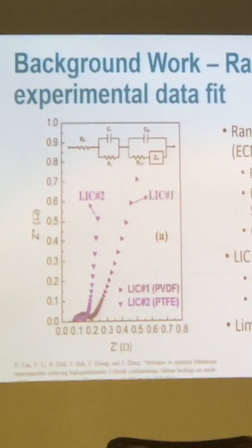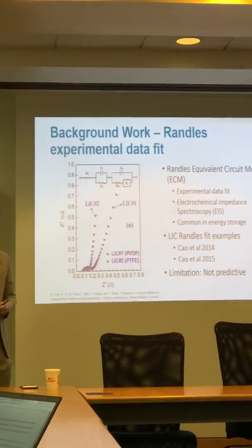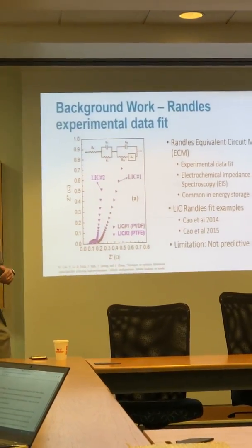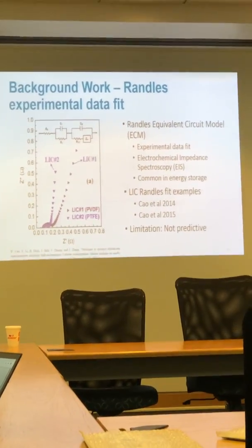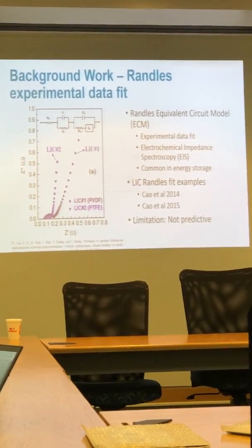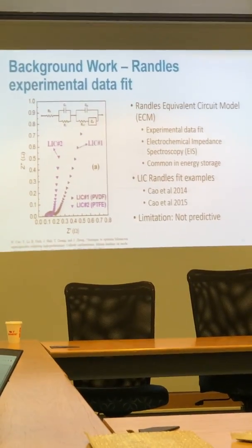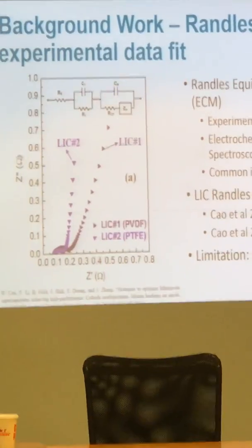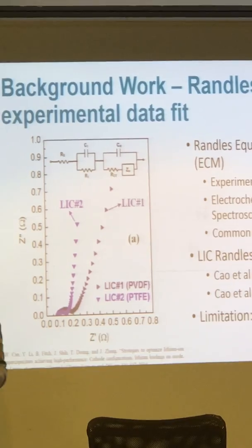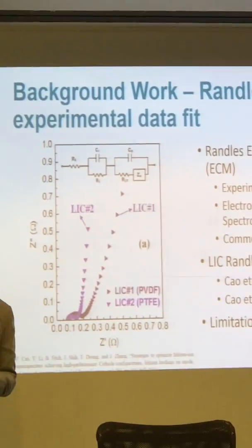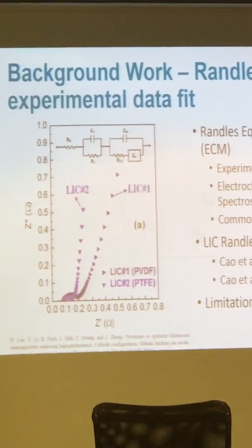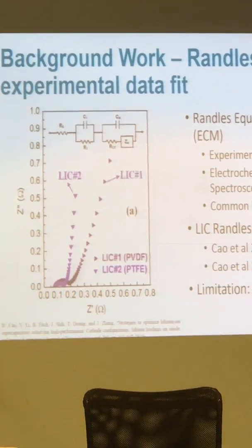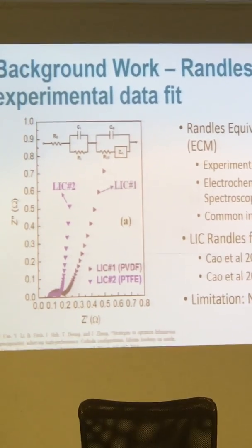Also, some of my colleagues at General Capacitor and at the Air Propulsion Mechatronics Energy Center across the pond here, we were in the lithium-ion capacitor business, and we did a whole bunch of electrochemical impedance spectroscopy tests, developing these nice Nyquist graphs, and from there we could build a Randles equivalent circuit model that does a good job of telling us how this device performs. This is very good for characterizing a pre-made device, but remember, these are not predictive.